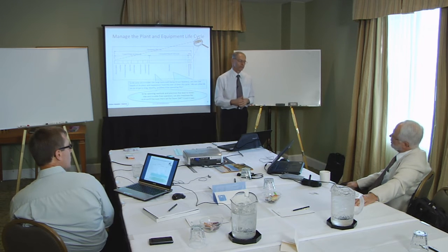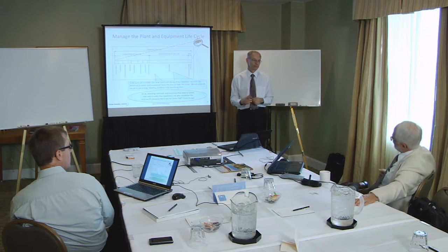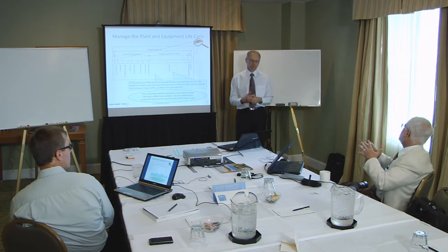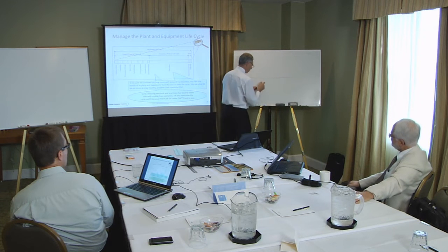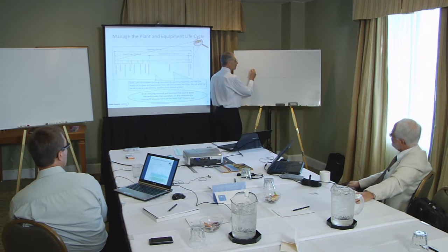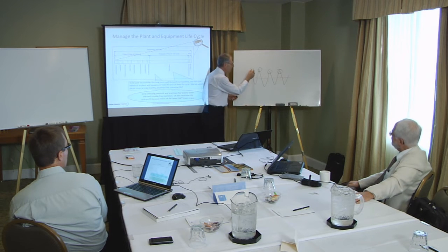I heard somewhere that airplanes that make short hops have a greater degree of fatigue, because the pressurization and depressurization is basically fatigue stress. Yeah. I mean, again, it comes back to as that plane's going up, the pressure's changing and coming down. So it's doing that to the body of the plane. And these are the ones that chew the life. So the guys count the number of flights and the duration of the flights because they know that must be reducing the life of those parts. And so after so many counts of up and down cycles, rebuild or replace. Every company should think the same way.